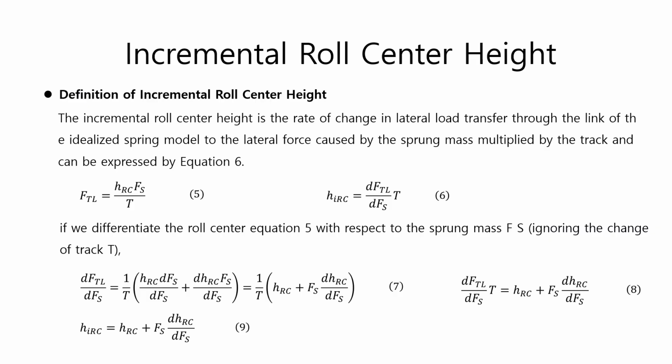Let's learn about the incremental roll center height. As previously discussed, when lateral acceleration is large, the difference between left and right tire reaction forces gets bigger and a jacking force is developed, which changes the height of the roll center. To understand how the roll center height changes as the lateral force increases, we need to introduce the incremental roll center height.